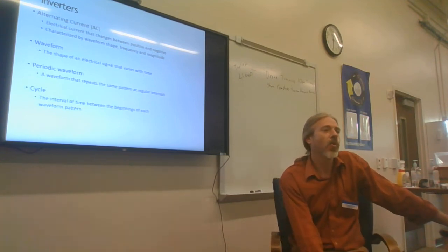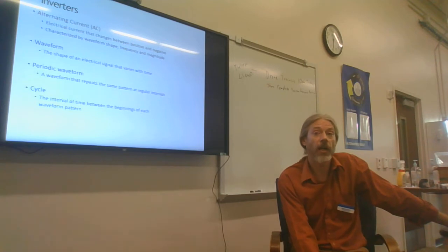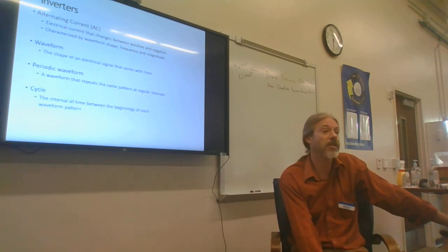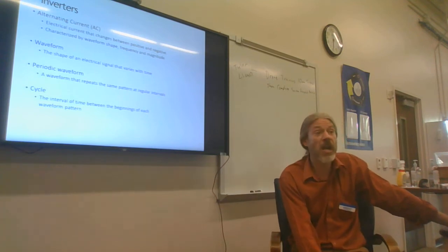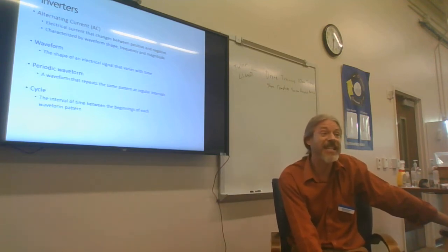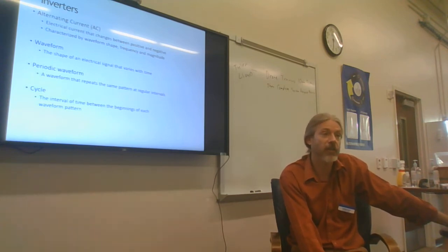In other words, what do the electrical characteristics that are coming out of the inverter look like if we were going to graph them on a graph or look at their signals on an oscilloscope? Some of them can be square. They can still be AC, but be square waves or square signals. On, off, negative, off, on, off, negative, off.